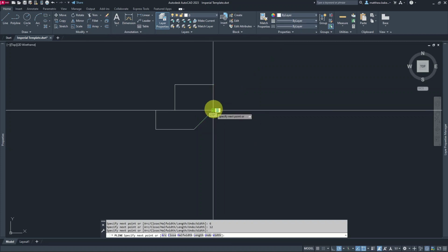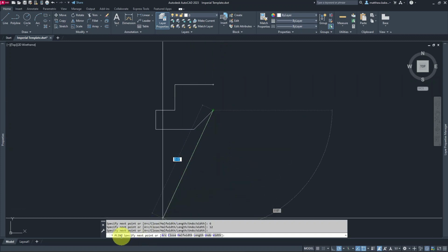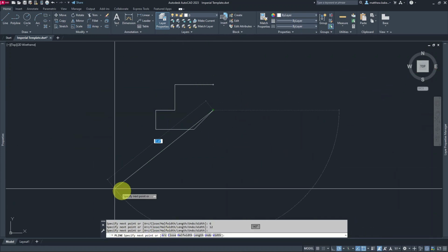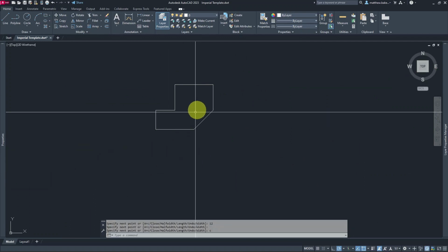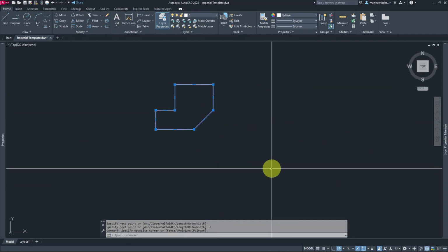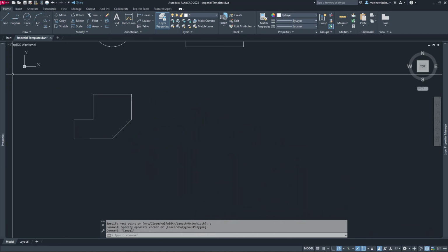So just click it, and then you can either hit C down in the bottom if you're paying attention to the polyline command, down here C to automatically close it. So no matter where you have the mouse, if you just hit C and then hit enter, it'll close it as one single object. Alternatively, you could just pick the endpoint as well.